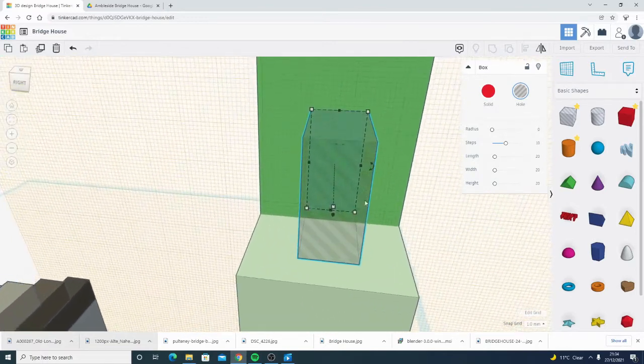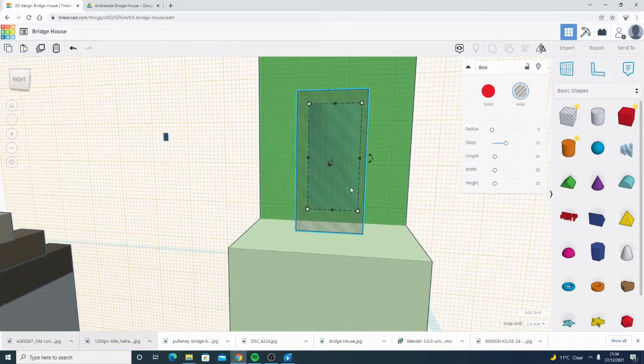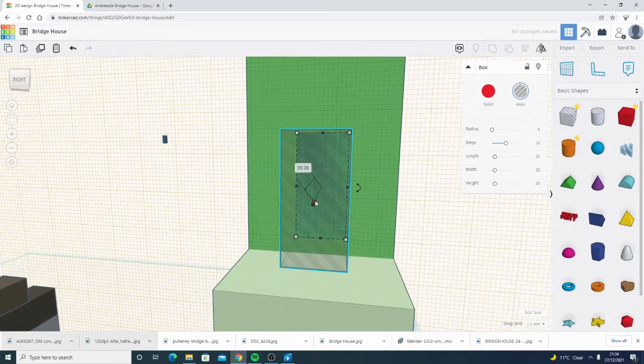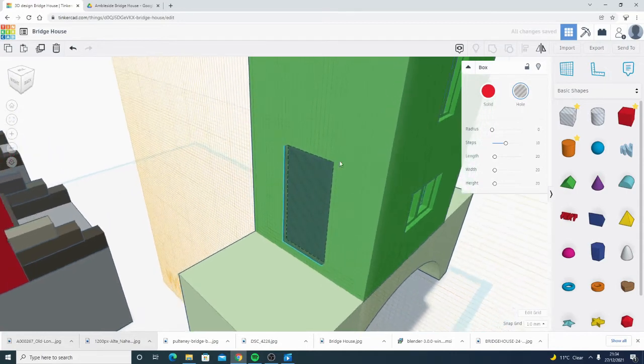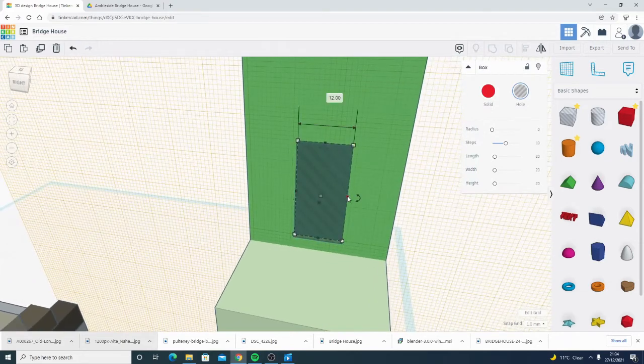Going to have a little bit of a step. Yeah, let's leave enough for a step. Okay, I'm going to push that in 1 millimeter to get the frame thing. So push in 1 millimeter. I'm going to duplicate that and have a slightly smaller part of that, which is the hole that's all the way through. So in fact, let's just move that duplicate out of the way for a minute.